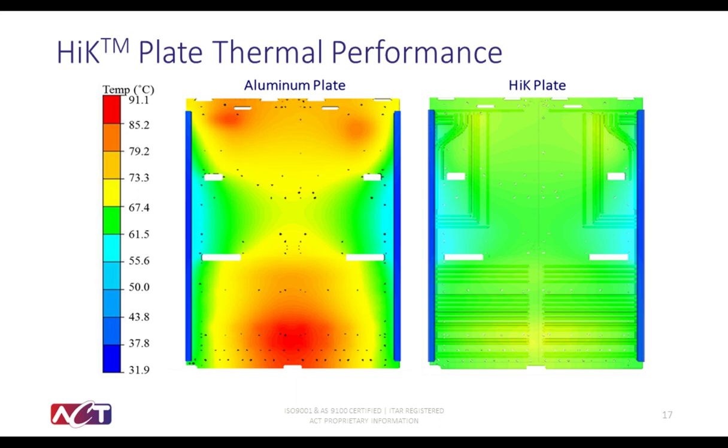The image displayed on the slide represents the thermal signature before and after heat pipes were embedded, creating the high K plate. Prior to the heat pipes being embedded, the electronic components were reaching 90 degrees Celsius, when their rating was 85 degrees Celsius. Since this plate was located in a finalized chassis design, the only thermal improvement possible was to the plate itself. The cooling rails, in which the plate were contacting, were supplied by a liquid at 40 degrees Celsius, much like our case study.